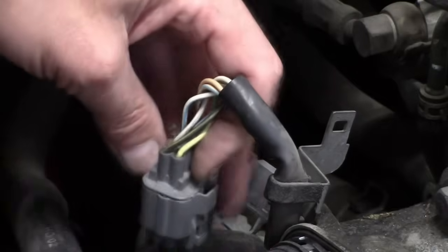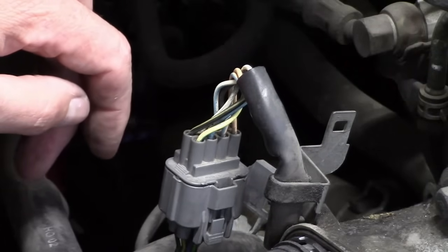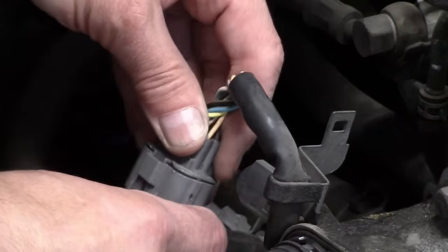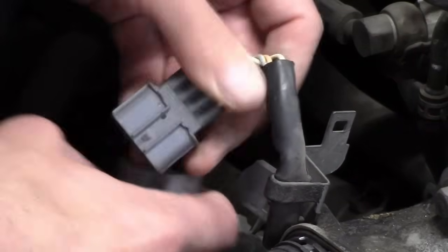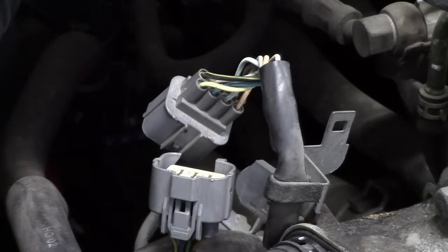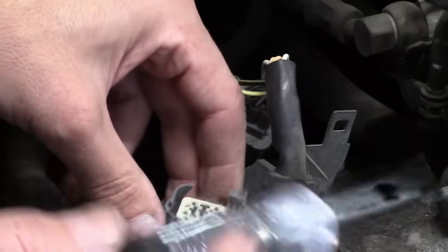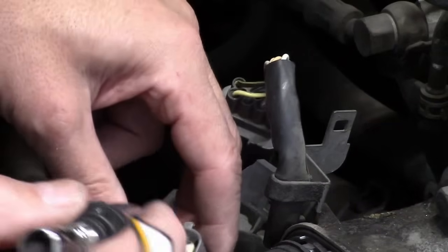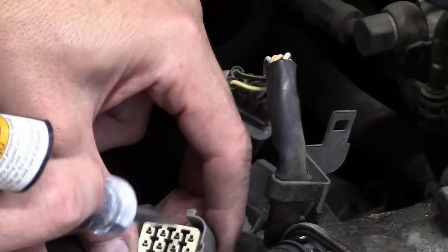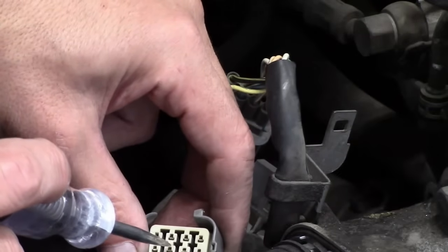So the only thing that I could do was, at least I do know there's going to be at least one 12-volt input into this, if for nothing else than the coil. So I disconnected the distributor and grabbed my test light, which of course is already at ground. I asked the kid to turn the car to on, but not start it. And I know from our basic ignition training videos that there has to be a 12-volt reference somewhere on here. So I went hunting and pecking for it, and I still don't remember which one it was.